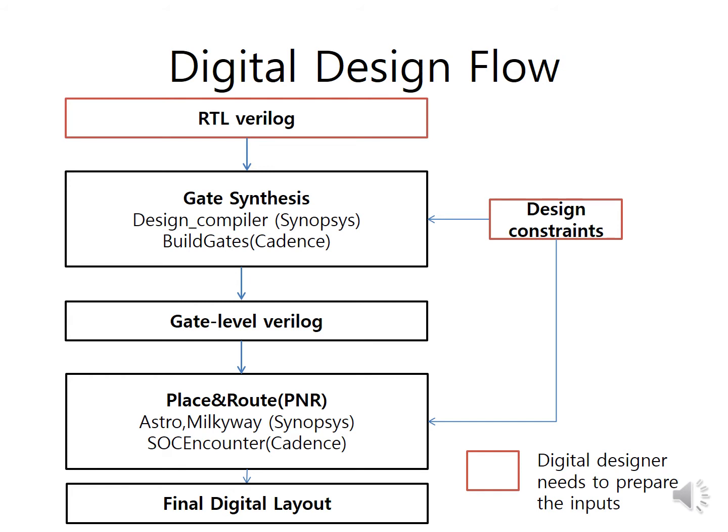Actual layout cells can be placed, and also routing is done. Whenever you make interconnections, the tool will do that for you. Not only does it connect the cells using wire, it also checks the timing between the cells, considering the wire resistance and capacitance.